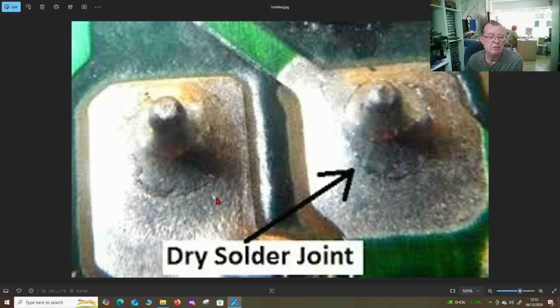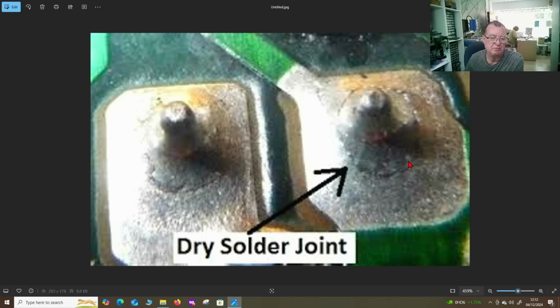And you should always have a look around the heavy components to see if you have this sort of problem. This is an easy fix. Firstly, it is just a visual check, which won't take very long because you're not having to look everywhere. And secondly, all you need to do is apply some flux and some fresh solder with your soldering iron, and you've fixed it. You can get these sort of failures on small components as well, but it's just less common. But never say never.